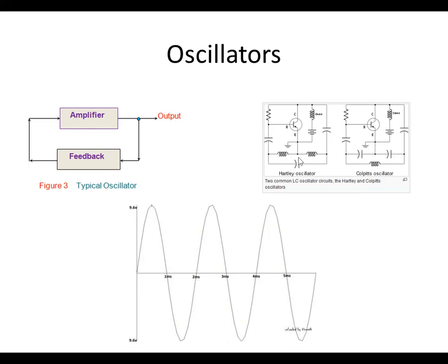They store energy and then re-release it at different times in the circuit. So this inductor will have current flow through it. It'll build a magnetic field, and then as the polarity of the signal reverses, that magnetic field collapses, causing current to flow into the capacitor. That increases the voltage. So this oscillator is essentially taking energy and shuttling it back and forth, storing it as magnetic fields and as electric fields on the capacitor.